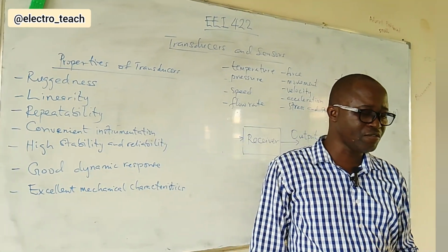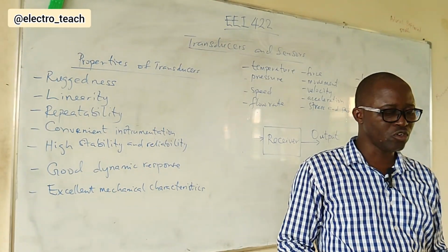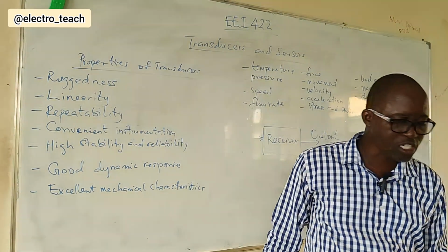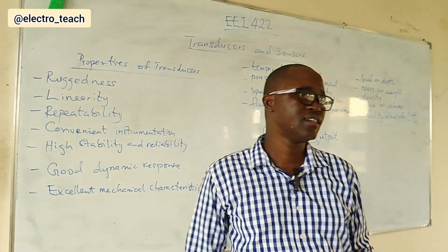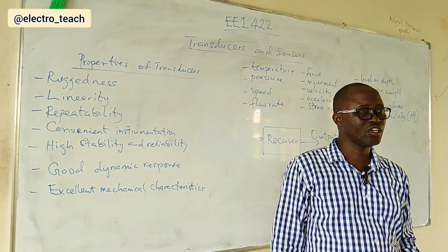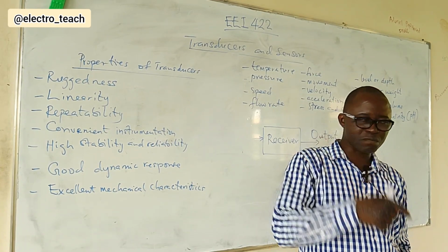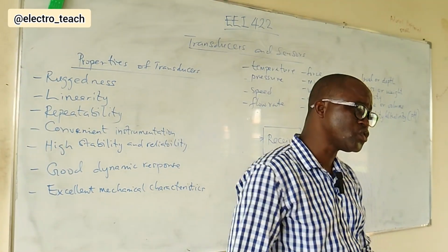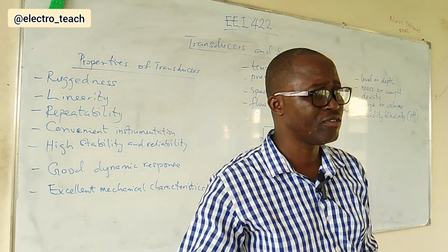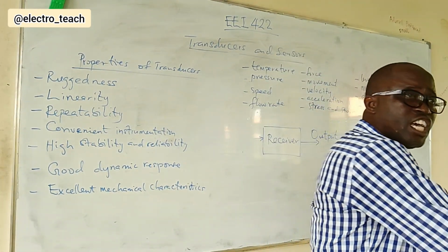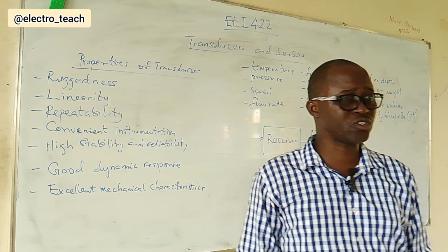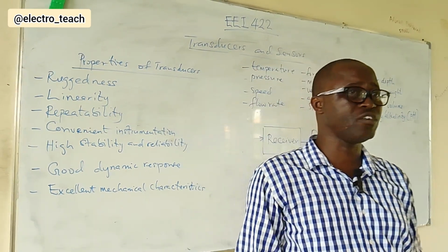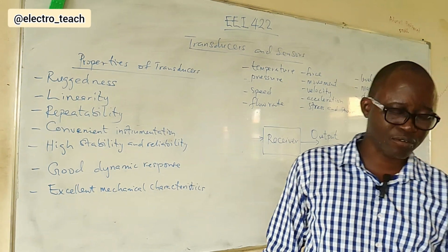Good dynamic response. A device that can give you faithful output with respect to input. Output is faithful to input when taken as a function of time. That is what we mean by dynamic response. That is, when the input is varying, how does the output behave? Is it faithfully following the changes at the input? When you have that, you have very good dynamic response. And this is taken as a function of time.